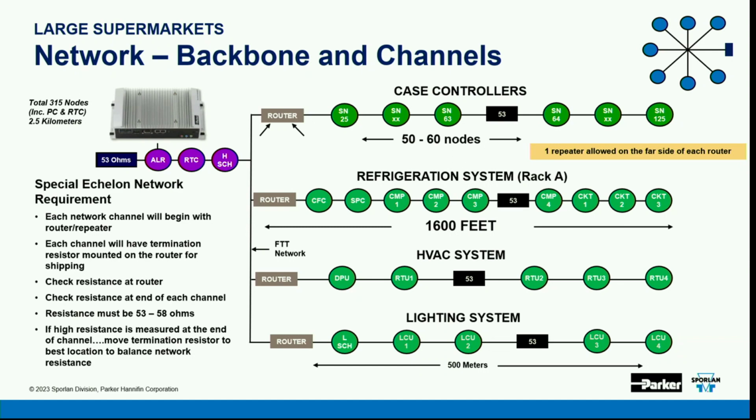You will lose your human-machine interface. You'll get a ton of alarms telling you you've got no comm, but the whole system is not going to go down because it's going to then synchronize to the real-time clock. If the real-time clock got smoked, guess what? All of these nodes have internal countdown clocks, and they will run off their own internal countdown clock. So that's a triple redundancy there if there's a problem.